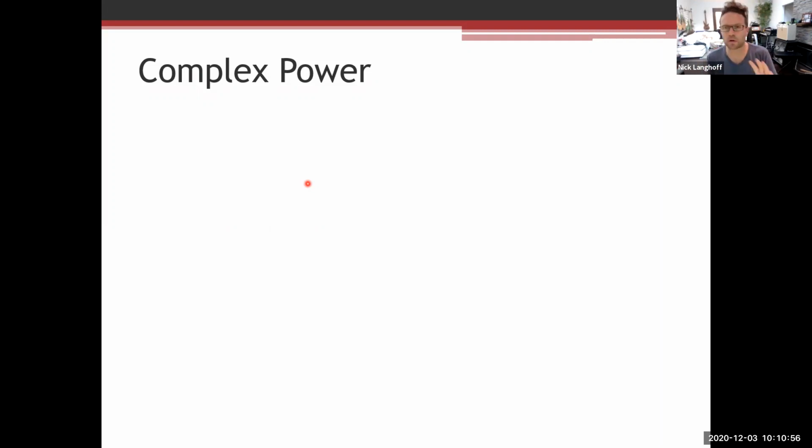And this tool of complex power makes the analysis much easier, and it in fact ties together all of the apparent, real, and reactive powers and the power factor into one nice, simple power to look at, and that's called the complex power, which we'll write as S.